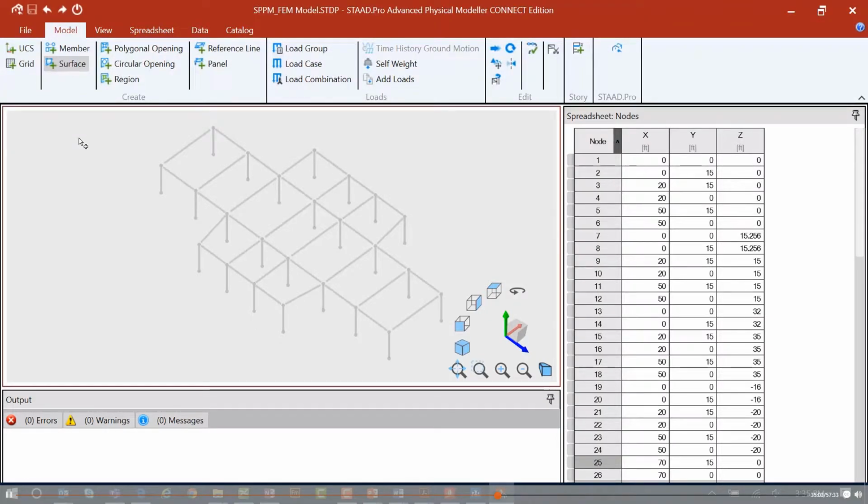Just like the parametric modeling workflow, it's not necessary to do one bay at a time. You can do your entire surface over your entire floor, and when the program creates that analytical model, it will recognize your interior beams and your interior columns as density points and assign the proper connectivity through nodes.